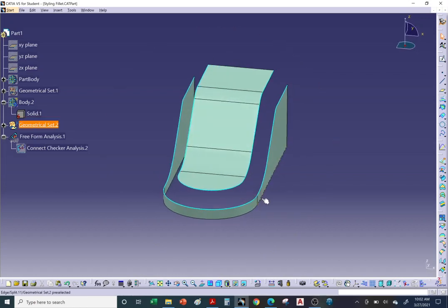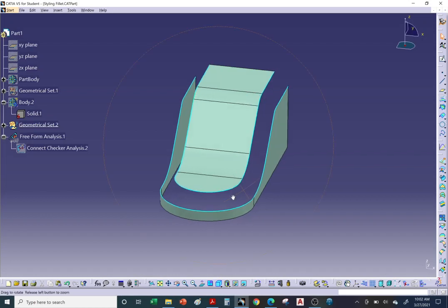Okay, so typically you want to save fillets for the very end, and that's also with solid modeling. And again, it's with edges that have twists and turns, right? You want to save those fillets for the end because you will get error messages. Your computer may freeze up on you. The software may freeze up on you. So expect that on complex fillets.